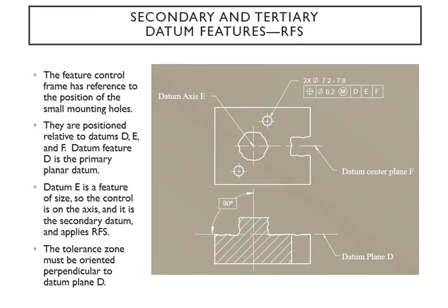Okay, so let's go into the next page. So here is your feature control frame. We're talking about the position of that two little thing right there, the diameter, your tolerance given to you with the max. When I say max, that's your maximum material condition, your little M right there.